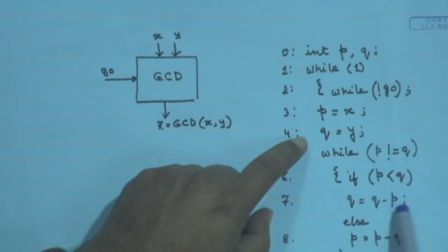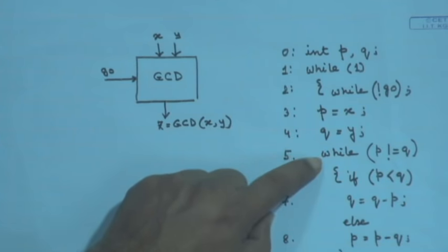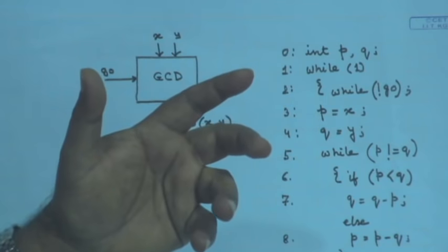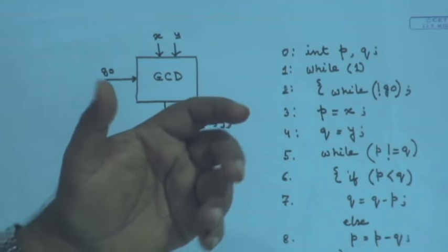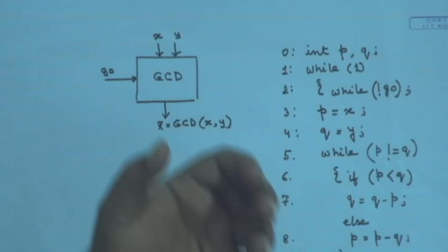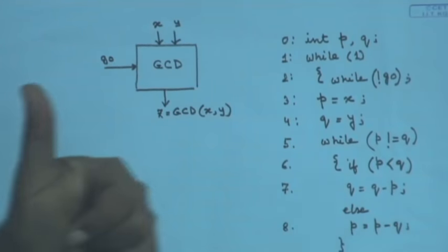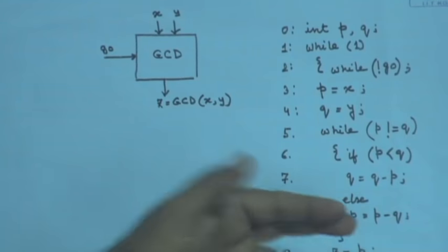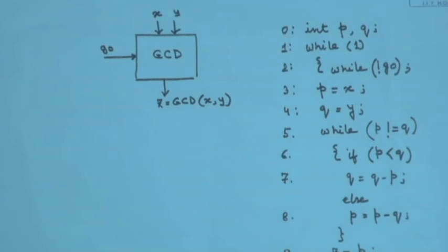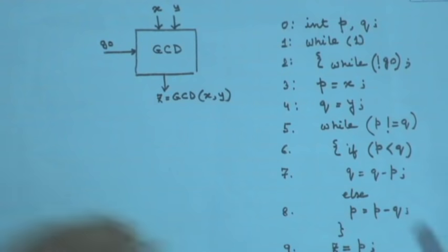Here, none of these operations are being done concurrently, right. So, I could have used one ALU for that. Now, I have to see whether the cost of the ALU is more than having them separately. A simple solution is, of course, the subtractor could be reused, or I can see if I can use the ALU also.